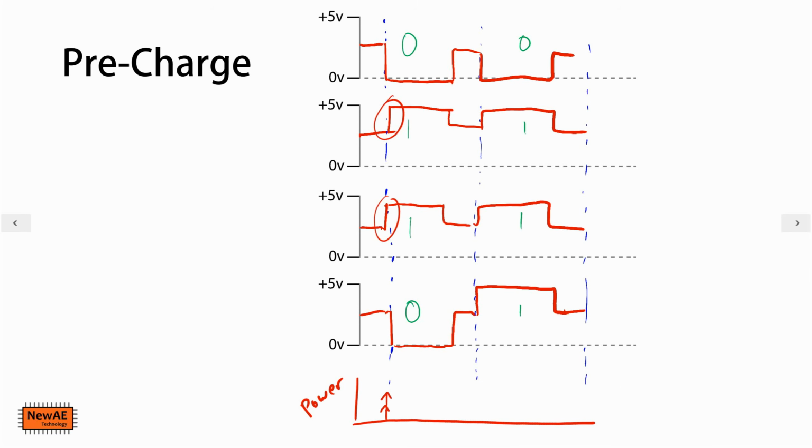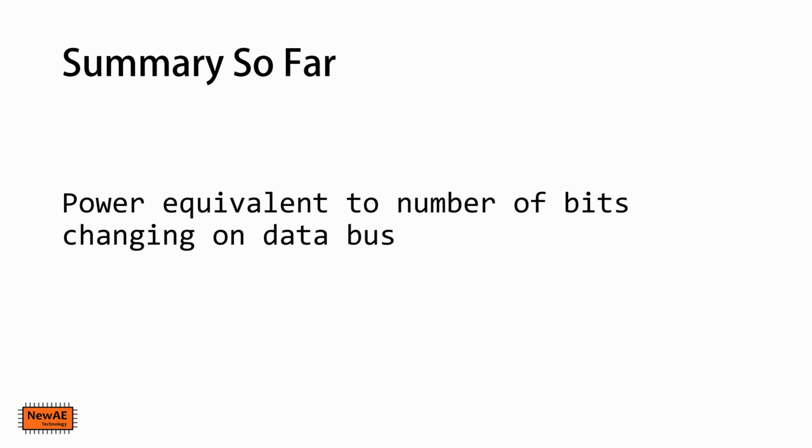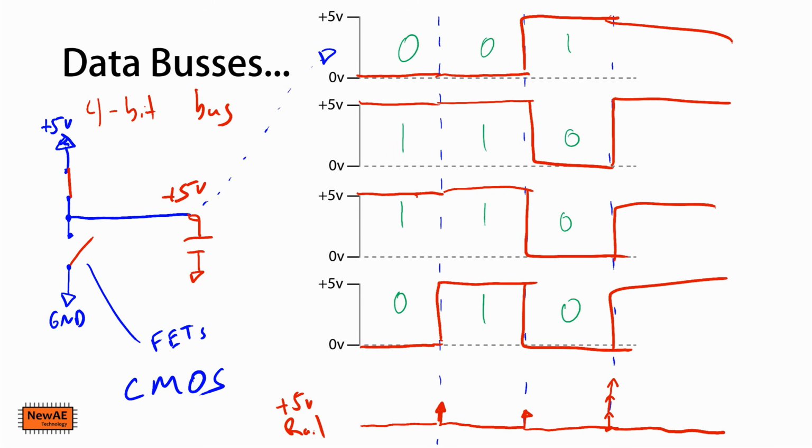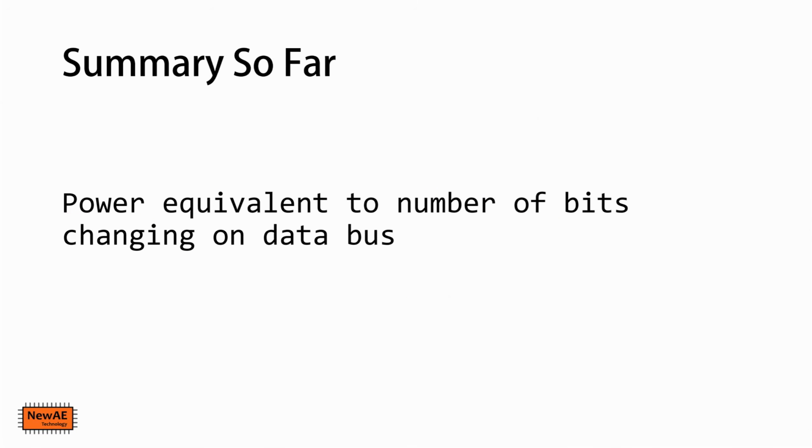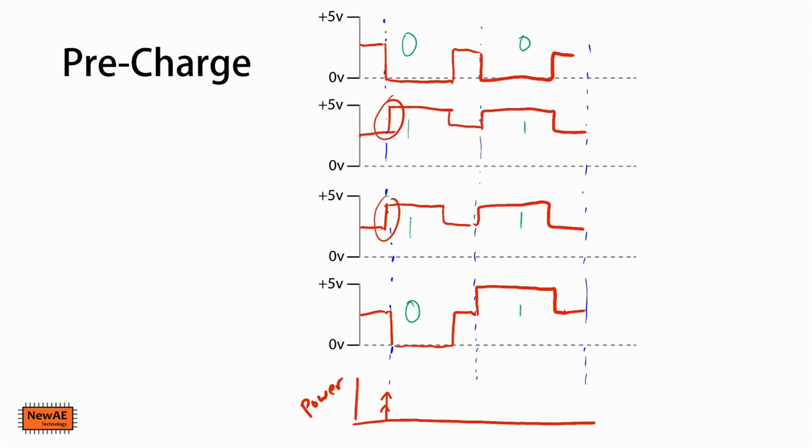Of course, the numerical size of this spike, if you could compare the 2 devices, wouldn't be as large because the swing isn't as high. That's the whole point. But we're just talking in units of the baseline of just one line being set high. In this case, where there are 3 data buses set high, you can see there are 3 transitions from the intermediate pre-charge state to the final high state.